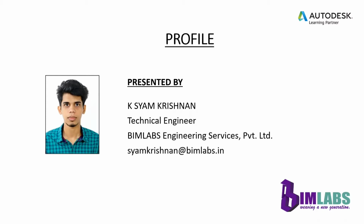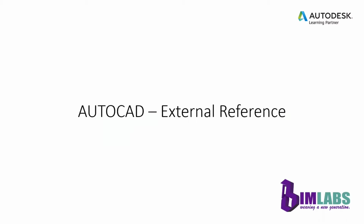You can contact me. And today in this tutorial video, I'm going to speak about external reference in AutoCAD. In AutoCAD, you can import drawings in a way that keeps the imported drawings independent of the current drawing. This type of file is known as external reference or XREF. Attached XREFs are linked to the model space of a specified drawing file.